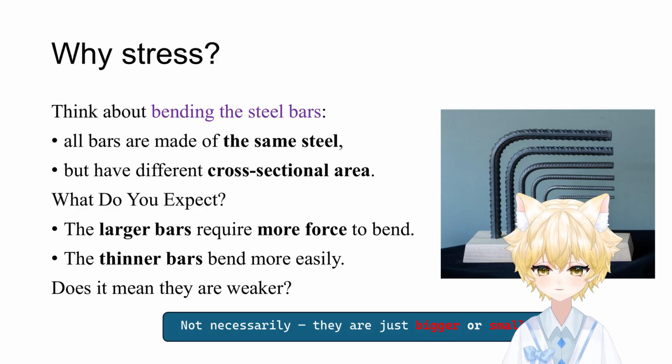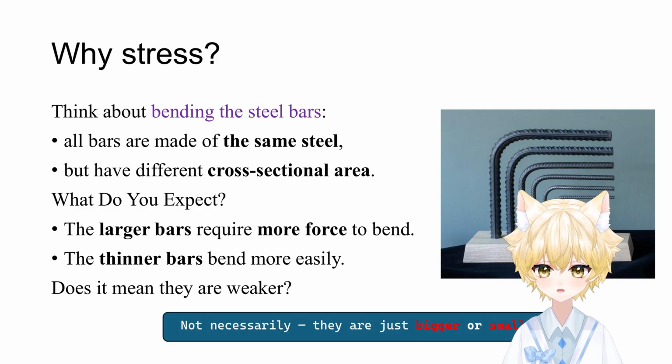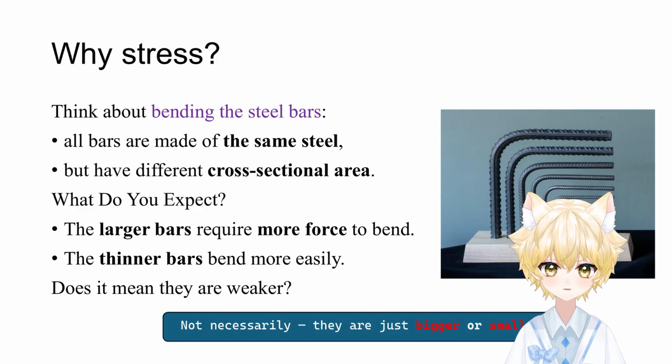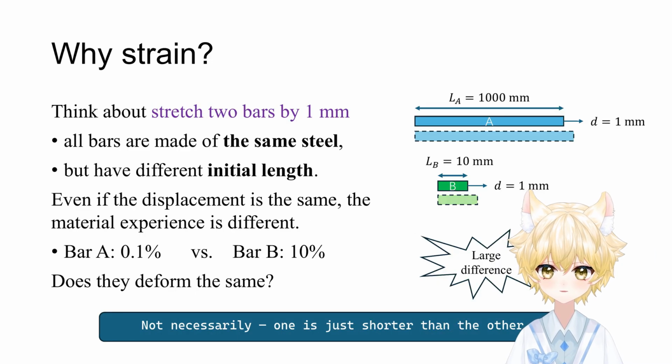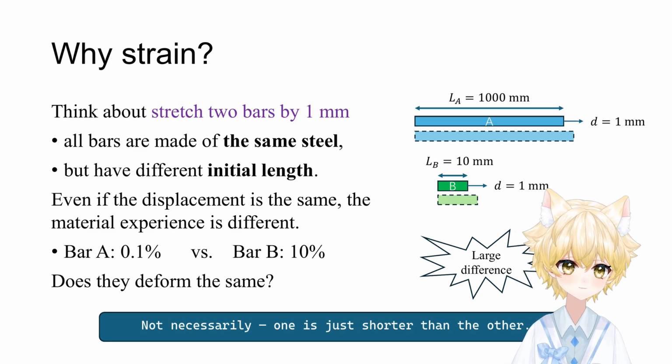This is why we introduce stress. Stress is the force divided by area. It removes the effect of size and lets us focus on the material response. Now look at strain. Think about stretching two bars by the same amount, say 1 millimeter.